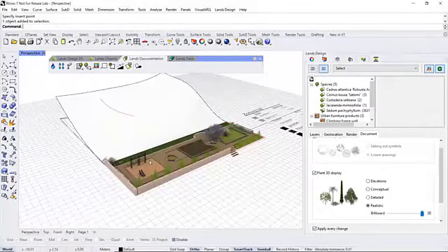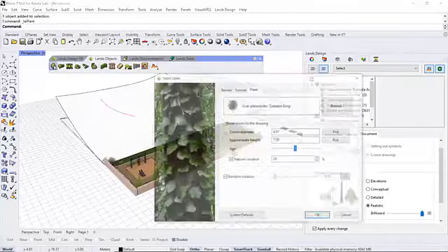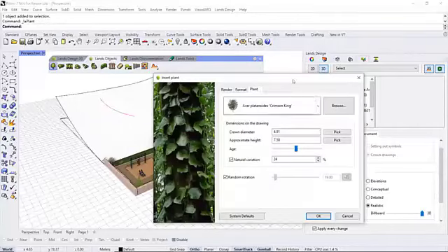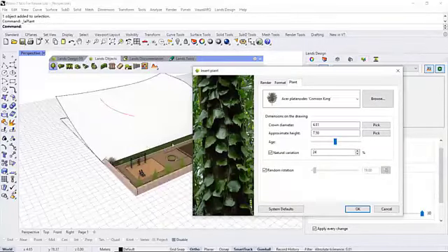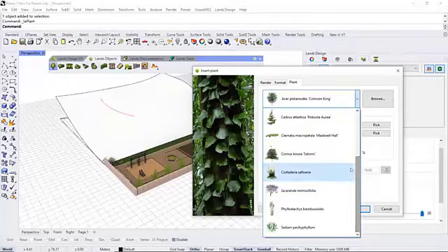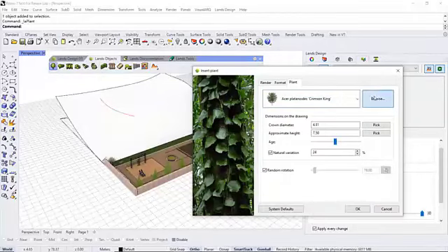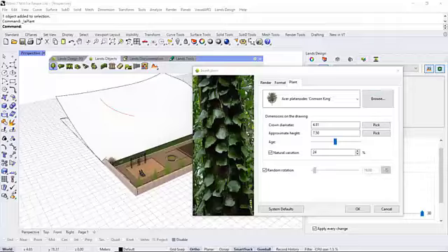Right. Let's insert a few plants here, so we see how the basic workflow of inserting visualization elements is. I'm gonna insert an individual plant right now. So of course, this is an existing document that already has some species here, so we can see the species that we have already used in this document, but we can browse the plant database for a new species.